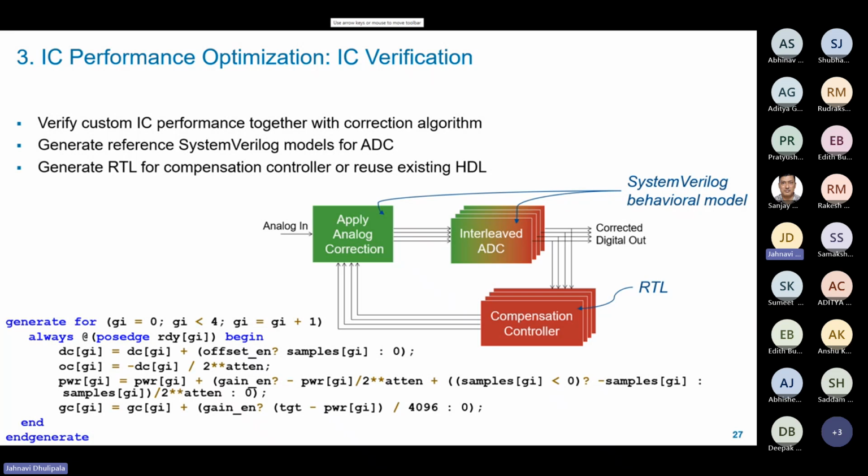For the ADCs, manual design is necessary since synthesis isn't feasible. So a behavioral model will speed up the verification of your complete model. You can directly generate the RTL from Simulink, and you can create the synthesizable Verilog or VHDL, or you can use this HDL in your pre-developed IPs. The Verilog implementation of the compensation controller is very effective and straightforward.